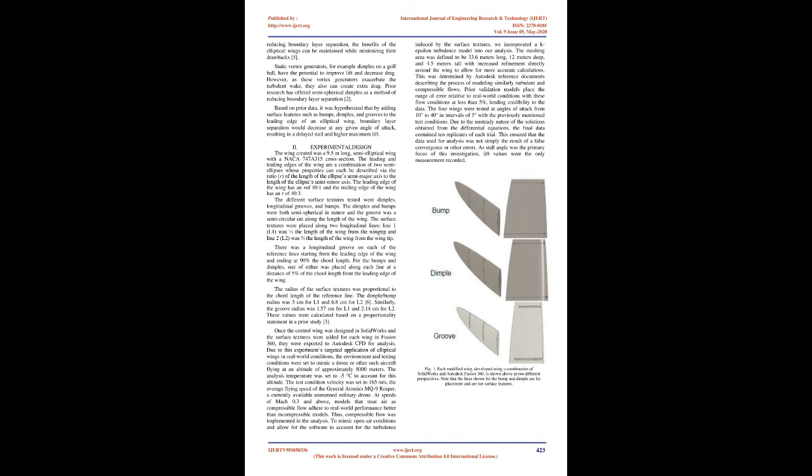Pressure drag is typically a product of boundary layer separation, the idea that the airflow around a wing separates to form a wake behind the body. A turbulent wake occurs beyond the point of separation, leading to pressure drag. This problem is exacerbated at higher angles of attack, during which the point of separation moves closer and closer to the tip of the airfoil. At a certain point, the boundary layer detaches, leading to stall and the airfoil having no lift.